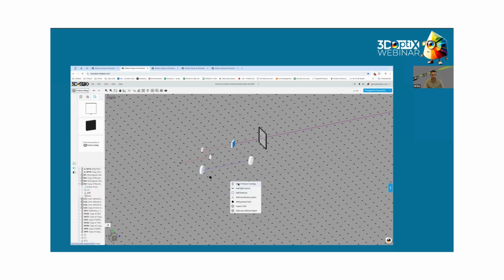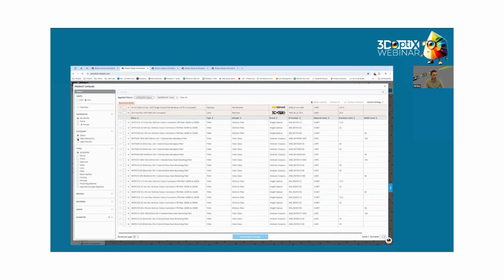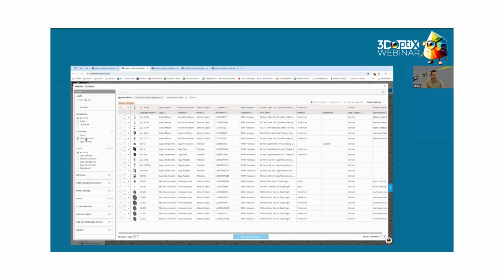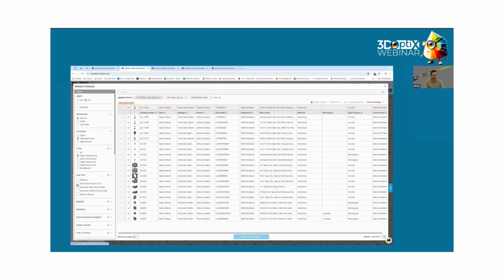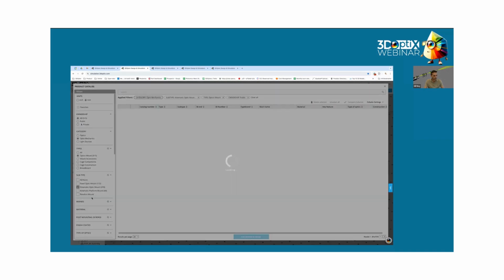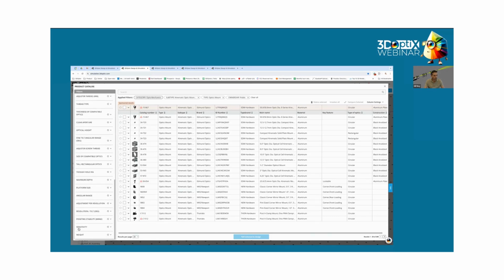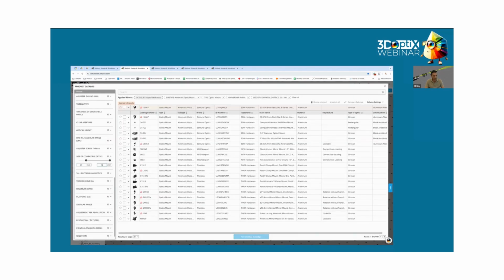So let's bring one of the kinematic mounts that would fit here. So I would select optomechanics, and then in the type, optic mounts, and then subtype, I would take kinematic optic mount. And then I would scroll all the way down and then a little bit up. And then I would look for the optic size, so size of compatible optics. Since I used 1 inch, I would do again 25 to 26.